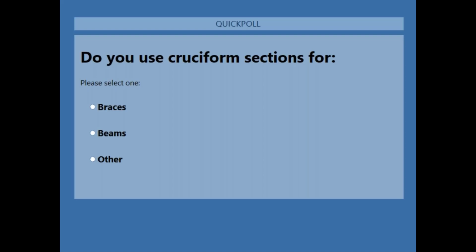Basically, what we're doing is we are allowing you just like we normally would. But if they're referring to being able to get the hand in back to put the nut on, which I believe the question is asking, that's up to you to make sure that there's enough hand space to get around and put the nut onto that, or choose another connection type like a shear tab or a double angle connection welded to the supporting member. So that's how I'm understanding the question, that they're looking for being able to get their hand in back to be able to check.